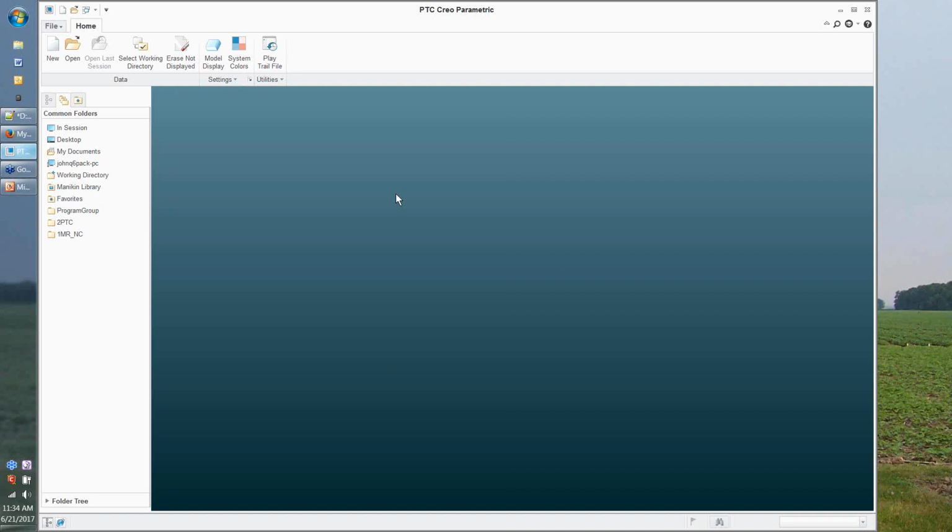A little bit about where we're going with this webinar is the Import Data Doctor environment and import data repair within the Creo Parametric world. We use the Import Data Doctor interface. This is the place where we're going to fix up the typical problems that occur when we're importing files from another system provided in a neutral format. Something provided to you as a STEP file, or alternatively, a worst case scenario, maybe an IGES file.